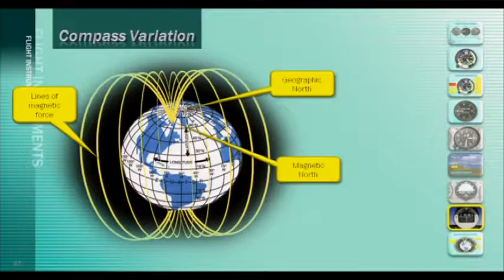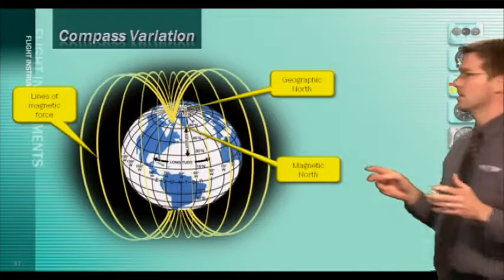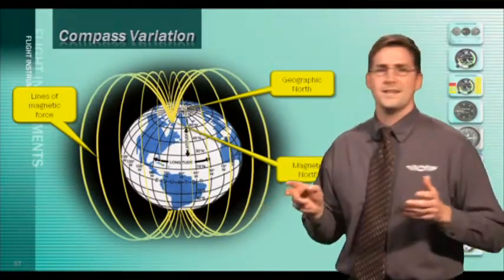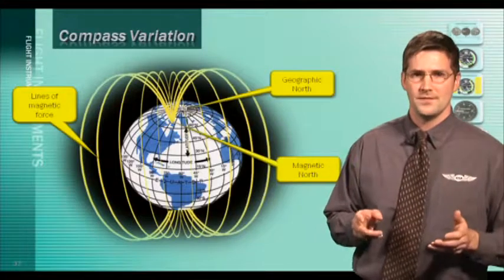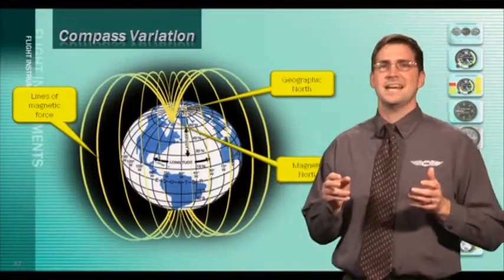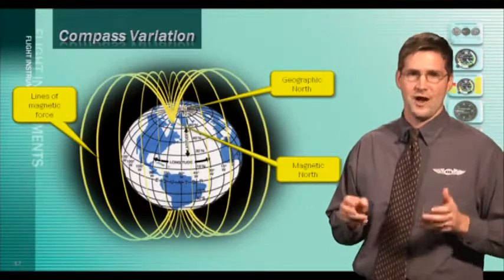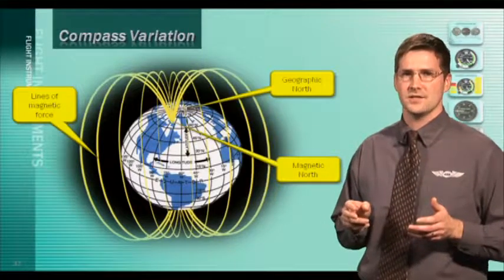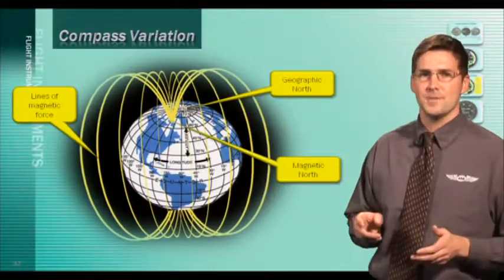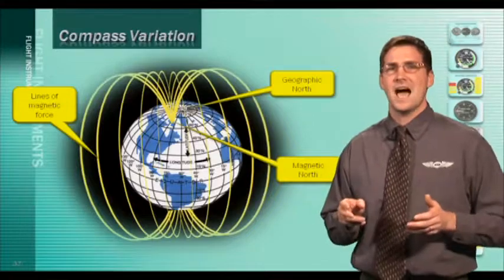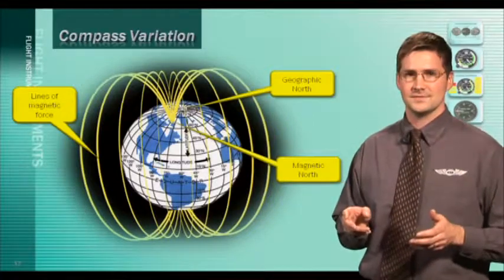The compass magnet is aligned with the magnetic poles while aeronautical charts are orientated to the geographic poles. The variation must be taken into consideration when determining an aircraft's actual geographic location. It is indicated on charts by isogonic lines and is not affected by the airplane's heading.